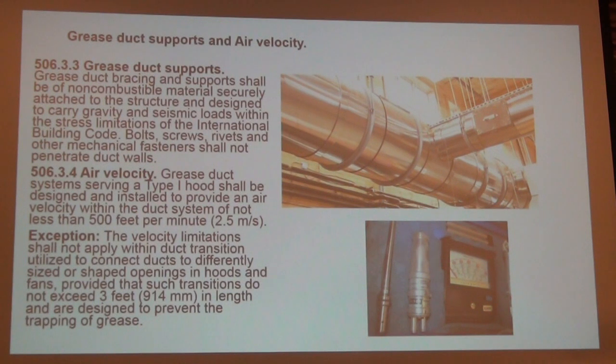But because of that, and I didn't even realize it, gas furnaces have some sort of safety device if the vent gets blocked, but oil furnaces don't. But in 2021, if and when we ever adopt it, of course we don't see much oil around here, it's mostly northeast. But believe it or not, I went on the internet, and there have been several cases of animals getting trapped in oil furnaces and killing people. So the 2021 code is going to require that all oil-fired appliances have some sort of vent blockage switch in it. Nice. Because of that reasoning.